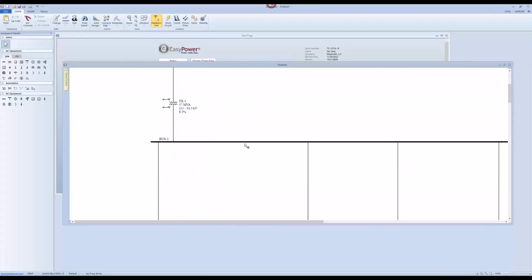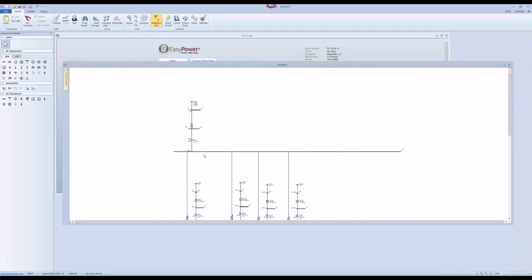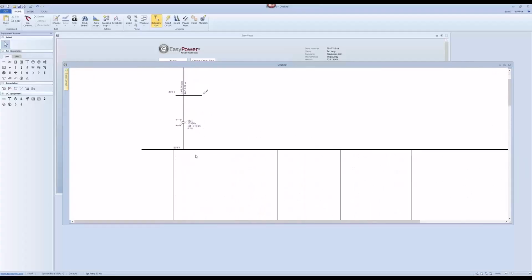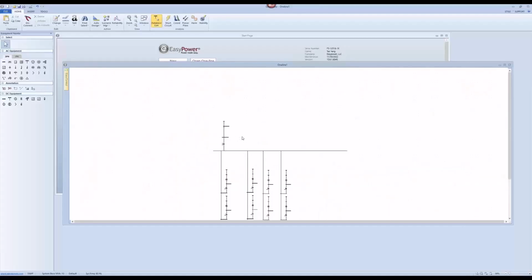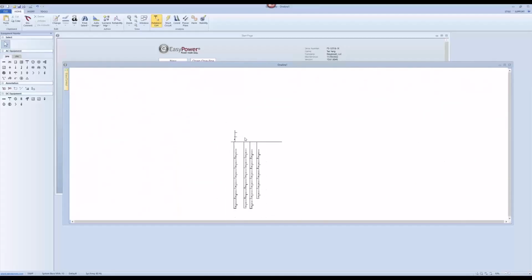Or another way to mitigate that is very simple: you design a harmonic current filter, right? At the 34.5 kV, so all those harmonic currents will go through the filter instead of going through the main power transformer and to the utility and creating your TDD, right? Or the current distortion, or demand distortion, sorry, not harmonic distortion. Harmonic distortion applies to voltage only. Current is the demand distortion. So that is the whole process of evaluating the PV portion.